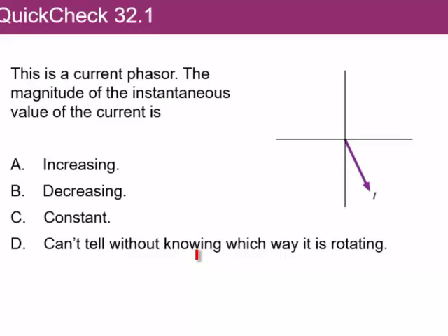And I'm going to assume that you did that, and here's the answer to this question. The answer is that it's increasing, because by convention we said that the phasors would always be going counterclockwise. So if we see it at this instant, it's going to be going later to something that may look like this, if I can represent a vector like this. And so the projection on the horizontal axis is actually going to increase, and that's why we are in a phase where this is increasing. As the vector rotates counterclockwise, its projection on the horizontal axis will be increasing.